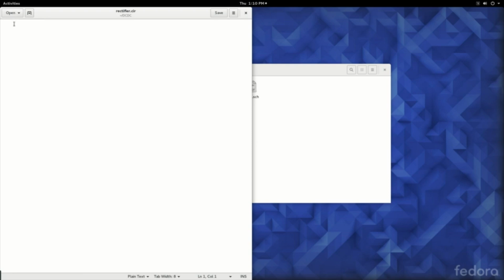and here the first line is always a comment. So start from the second line. We would like to have a transient analysis performed, step time of 50 microseconds up to 100 milliseconds using the initial conditions.